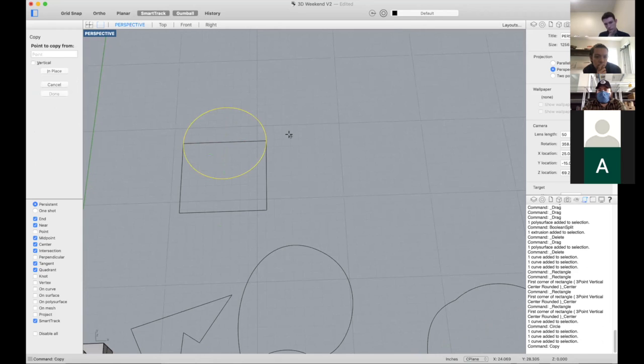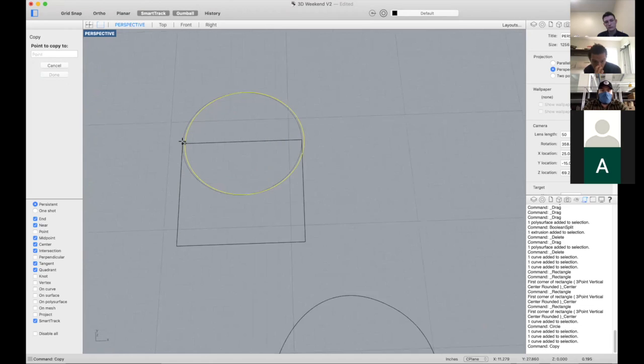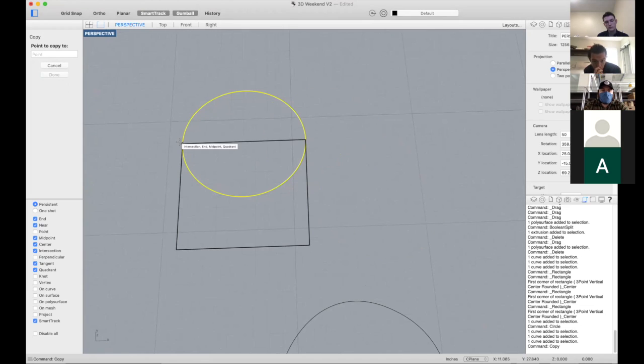This is not like copying in the way that you can then paste. This is the copy command. You can also just type Command C, Command V, and it'll copy whatever you clicked and paste it exactly in the same spot. But this is the copy command, so this is a little bit different. You click on the point that you want to copy it from. In this case, I want to copy it from here because that point also exists on the bottom.